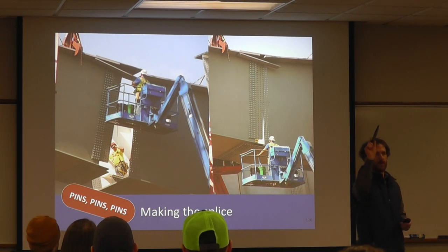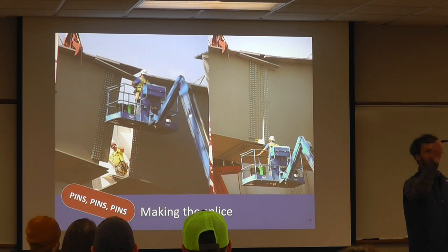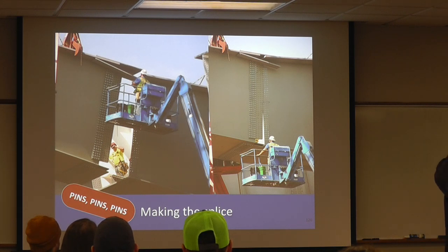We'll talk a lot more about these drift pins. You can see it has a tapered end on both sides and then a full barrel. That full barrel is to match the hole size, not the bolt size. So if we have a 7/8 inch bolt, that barrel is going to have that plus 1/16. That makes sense? Why do we do that?